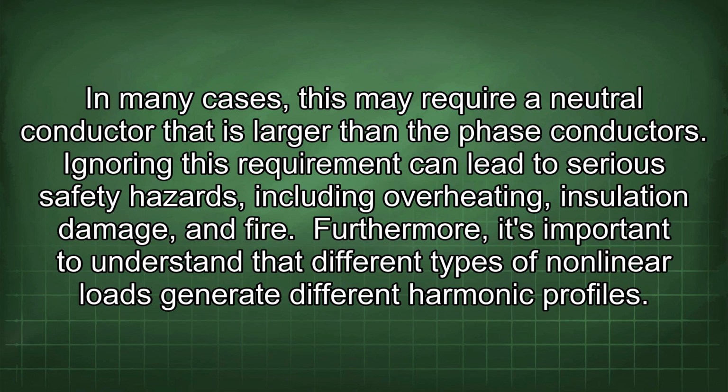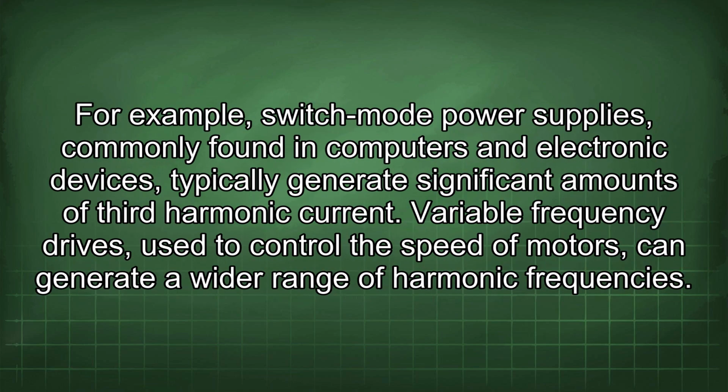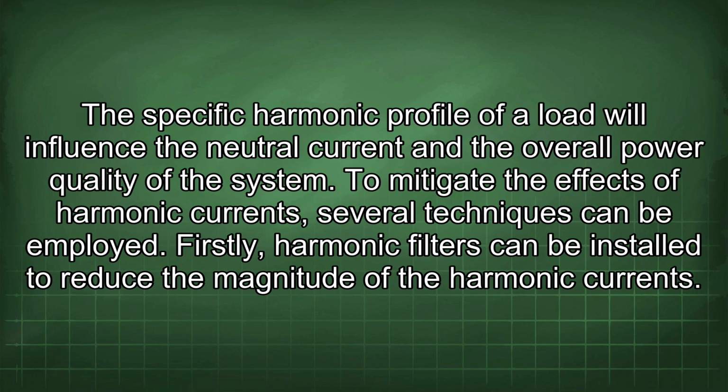Furthermore, it's important to understand that different types of nonlinear loads generate different harmonic profiles. For example, switch-mode power supplies, commonly found in computers and electronic devices, typically generate significant amounts of third harmonic current. Variable frequency drives, used to control the speed of motors, can generate a wider range of harmonic frequencies. The specific harmonic profile of a load will influence the neutral current and the overall power quality of the system.